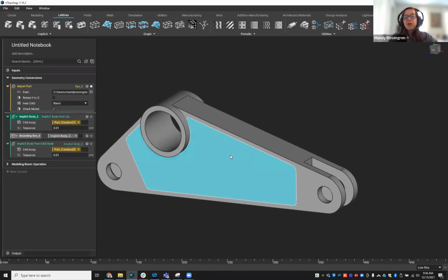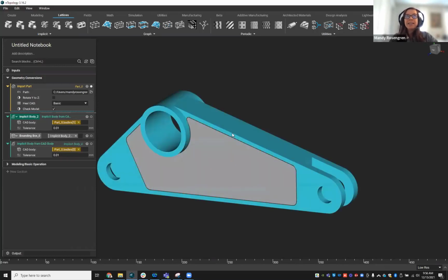If you brought in this inner body and this outer body separately, and you're having trouble orienting them, again, you could use those body properties, with that bounding box, moving it in those certain ways. But also, if you are working with multiple CAD parts, we recommend importing that part, such as a parasolid, something already split up, but as one file so that they will remain connected.